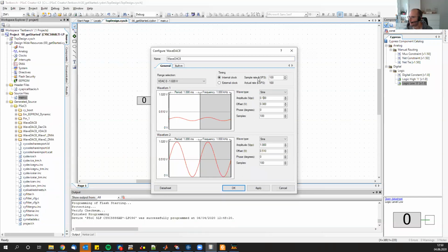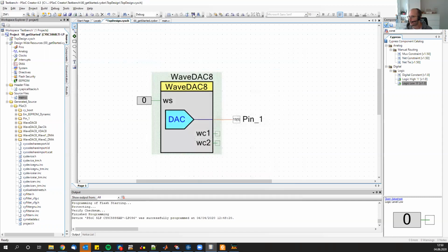And now we need to do a little math. So if we have 100 samples for that, and our sample rate is 100 kilosamples, then we will end up in a range of 100 kilohertz. I would say 100 samples here for that sine is pretty good. So if we, let's say, want to have 100 hertz, which is approximately the magnitude we talk about for our radar sensor, then we'll simply make that 10. So we end up with 100 hertz. Okay, let's simply try that.